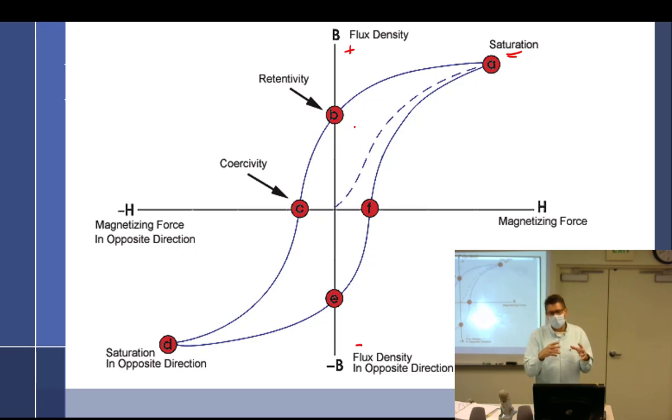Okay, so that's the continuous method, meaning that the fluid was put on while the power was activated. Now, you can't leave the nozzle on because you could literally wash away an indication. You want it wet and flowing, but not out of the nozzle. Okay, so that's continuous flow. The other one is where we can just magnetize something and then go, okay, now I'm going to get the fluid and put it on.